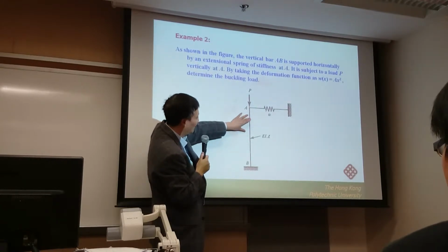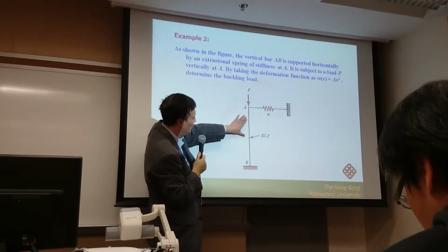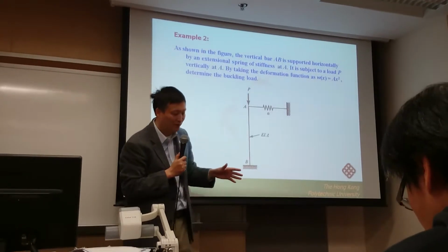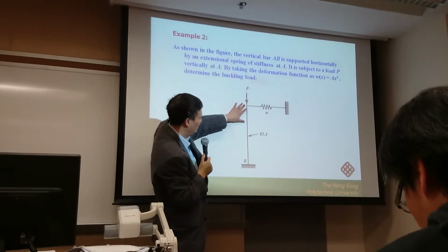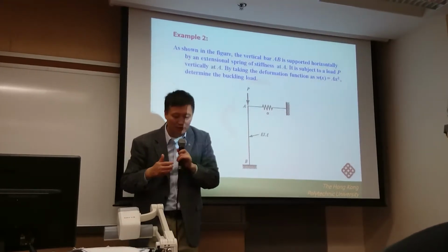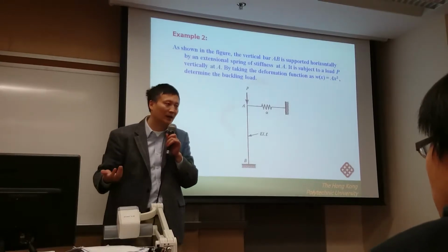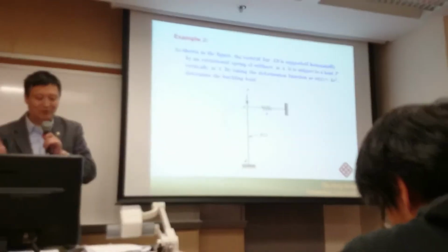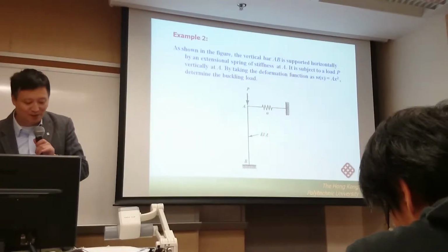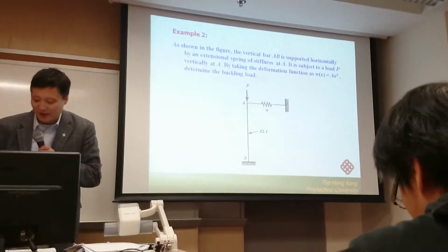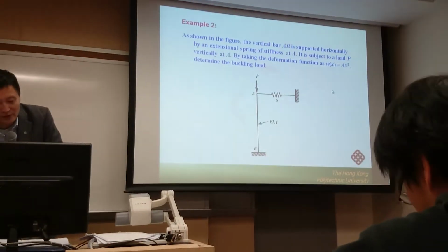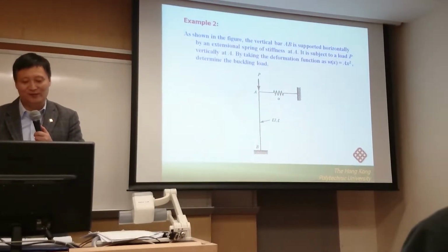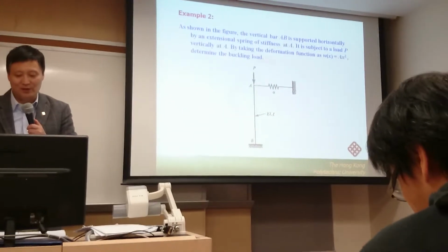For each segment, you can first obtain the total deformation for this segment, and then multiply by the corresponding negative applied force. For the first segment, it is equal to P, and for the second segment, it is equal to P plus 1.5P, something like this. So I provide you 3 examples, which already cover all past examination paper questions. So here we have 3 cases. It's very simple. Actually, in the examination, I just make a little bit of change like this.